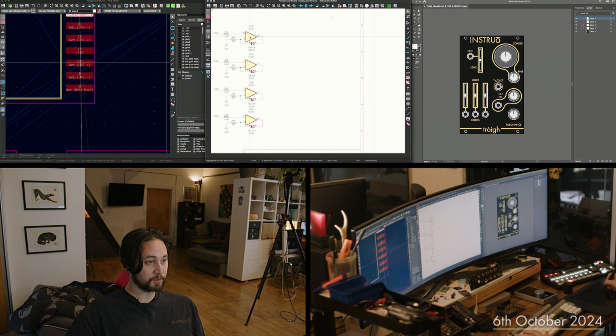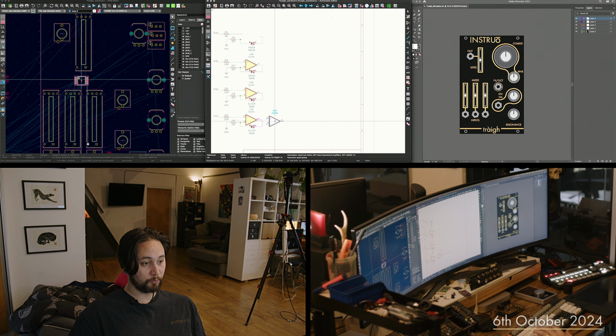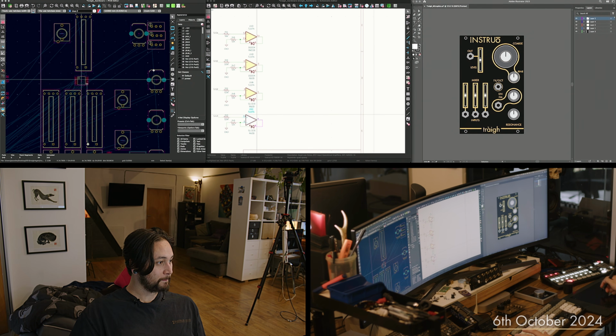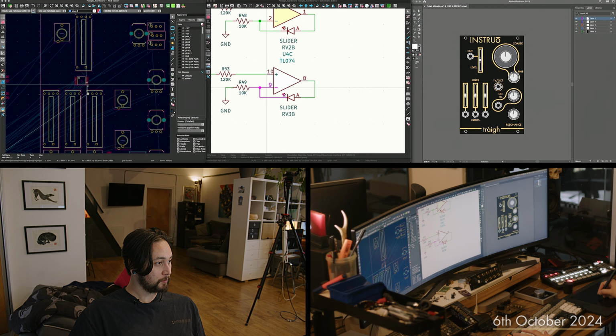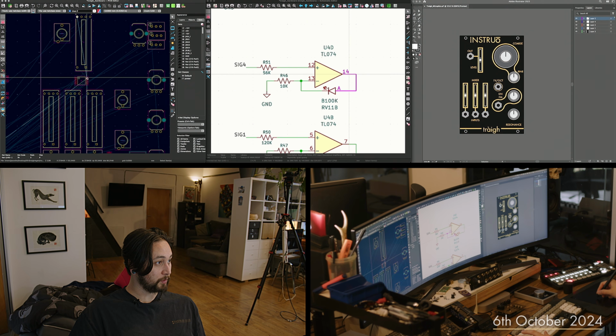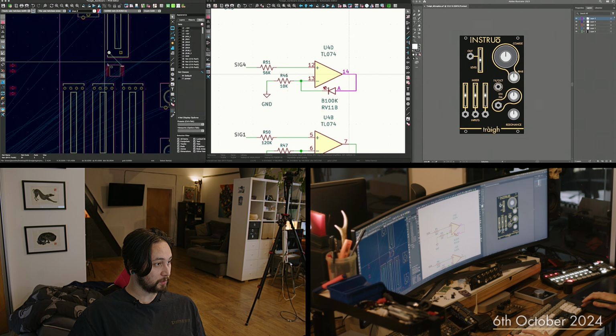So here, if I just select that, hit M for move, it moves it without moving the nets, versus G for grab, which lets you move it while staying connected to the circuitry. So let's try flipping these first. Okay, that's there. Then if I go with this one being the top, that's correct, and I might flip these ones.